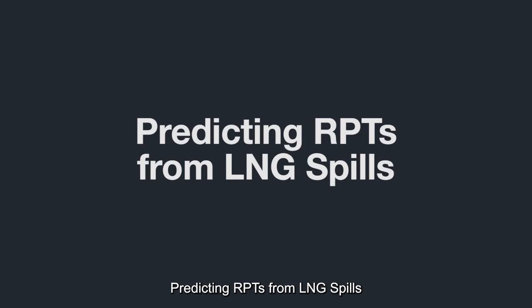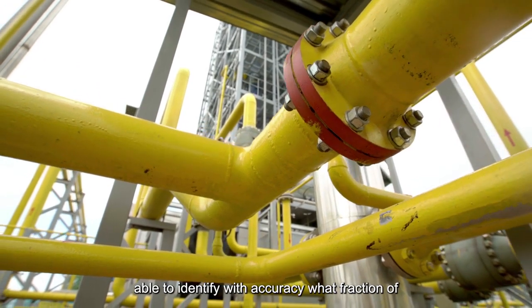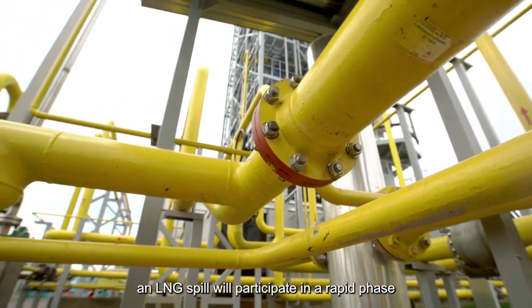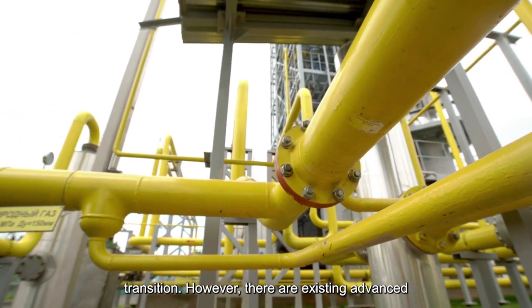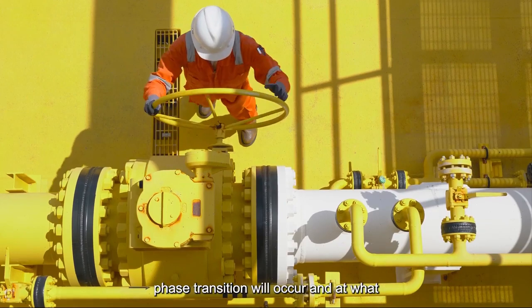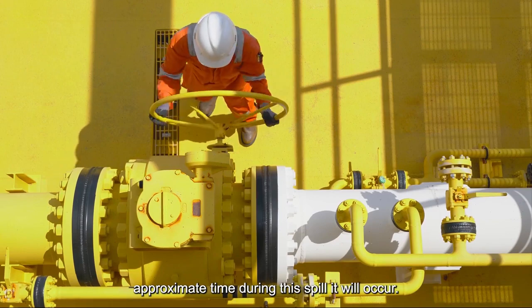Predicting RPTs from LNG spills. Existing modelling methods fall short from being able to identify with accuracy what fraction of an LNG spill will participate in a rapid phase transition. However, there are existing advanced modelling techniques that can tell us if a rapid phase transition will occur and at what approximate time during the spill it will occur.